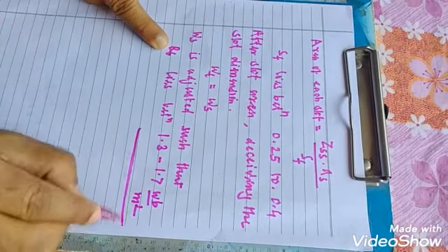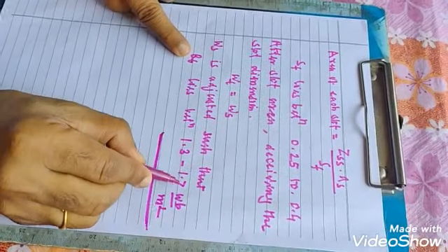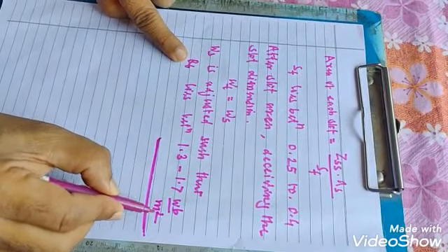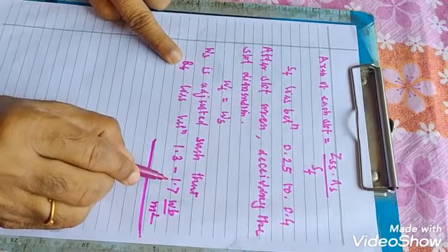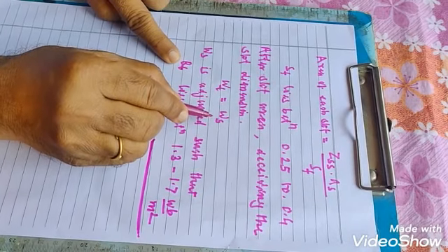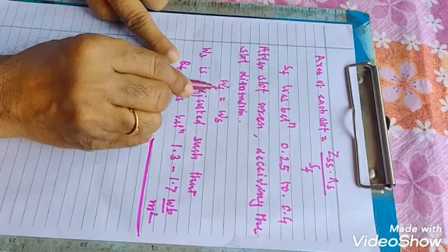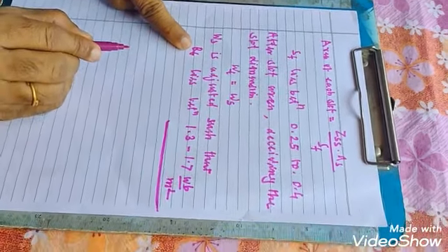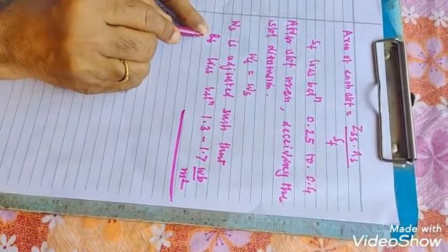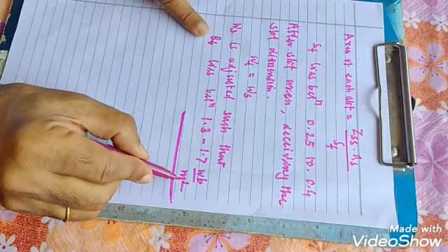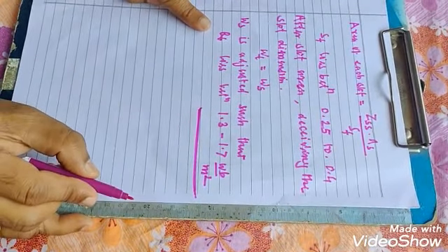This is important. If BT exceeds, if we select a wider slot, WS large, the area of teeth will decrease and the flux density will increase. So if flux density in teeth exceeds 1.7 Weber per meter square, then there is more iron loss in the teeth.